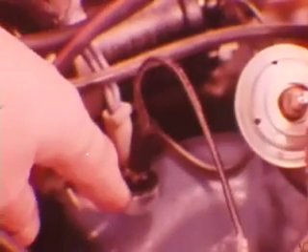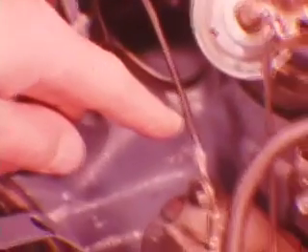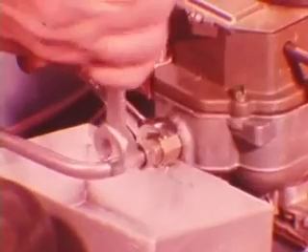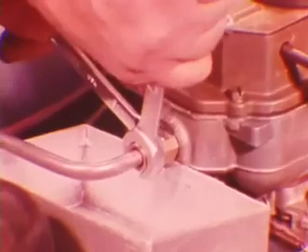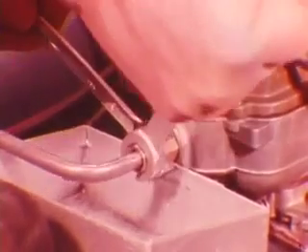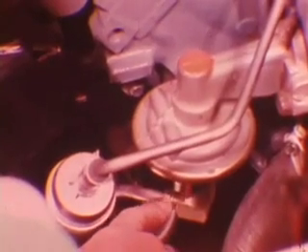And remember that a long delay between cranking and starting can make the choke come off too soon, due to electric choke assist action. Open the choke valve and work the accelerator pump. A positive discharge should appear in the carburetor throat when the throttle is opened. No discharge can mean that fuel is not reaching the carburetor. Loosen the inlet connection. Fuel should squirt out when the engine is cranked, but be careful. If necessary, do the same thing at the fuel pump connections.